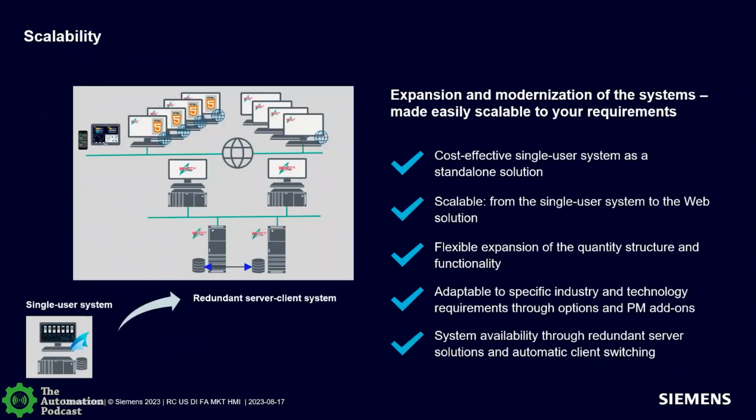Back to you. One thing with WinCC, we wanted to make sure we had not just a one-size-fits-all application. So it is a scalable system. It can start as just a single user system, with the PC talking to field devices, displaying local screens. Or you can take it up into large distributed systems. We can split the project up to 18 different servers. We can do redundant servers. We can have clients being other WinCC stations, or web-based clients, up to 150 different client stations. So it can start small and grow over time, or as you need to, you can scale it up to a very big system, which is the V8.